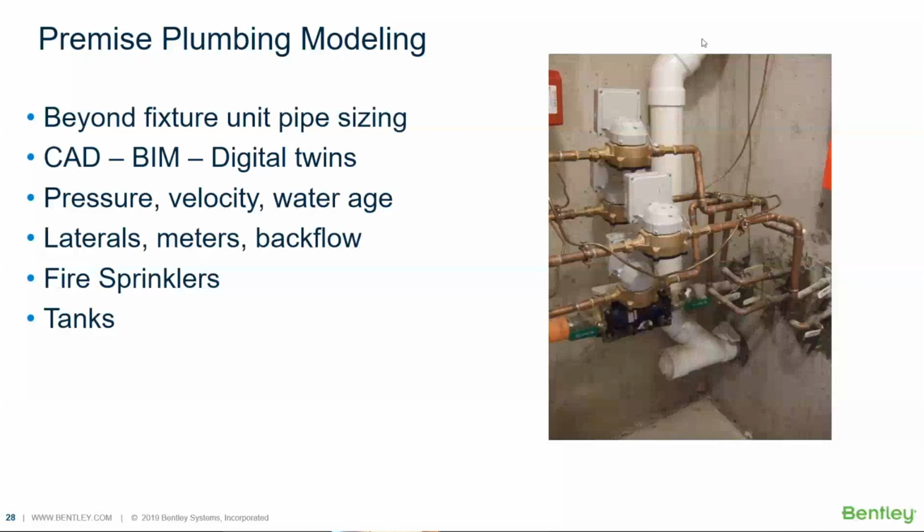Fire sprinklers can have some interactions with the premise system, depending on where they split, whether you run the fire sprinkler system through the meter, whether the fire sprinkler system is a separate service line, or whether it's a multi-purpose system, becomes a real issue. And finally, the existence of tanks in buildings is another twist that you can model and study in premise plumbing. So that wraps it up for me.